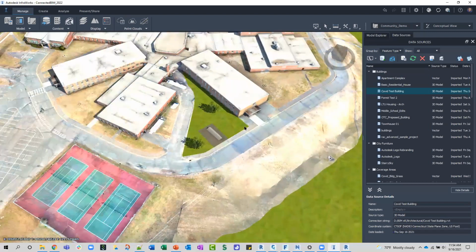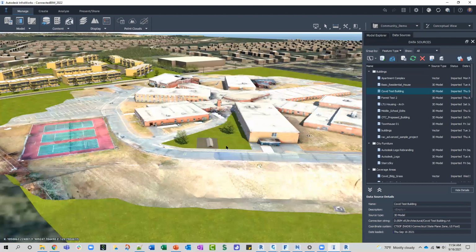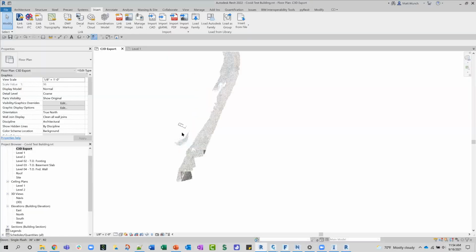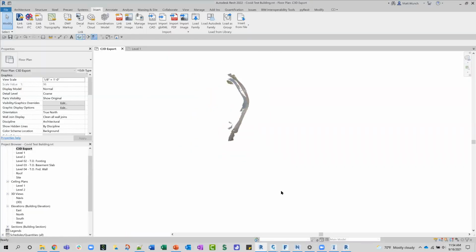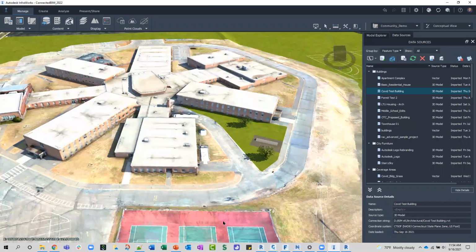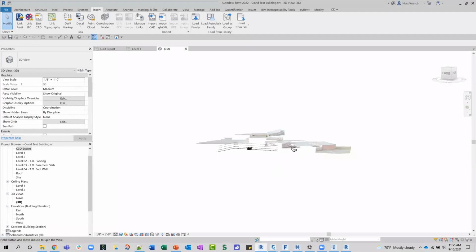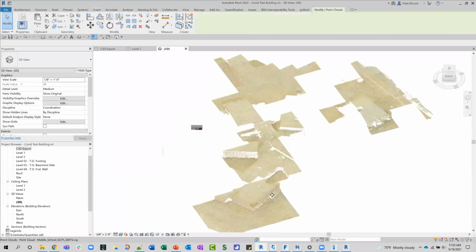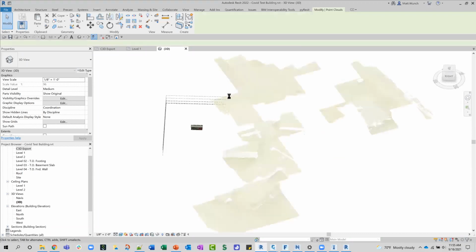So it wasn't set to the correct elevation, obviously. So one thing you want to take a look at, make sure you've got the, oh, look at that, it did. So yeah, just make sure, when you're doing all this, make sure your elevations, your levels in Revit are set. I did kind of gloss over that, kind of speeding through some of this. It's just chugging away right now. So it looks like it did bring in that point cloud in the right location based off of those shared coordinates.